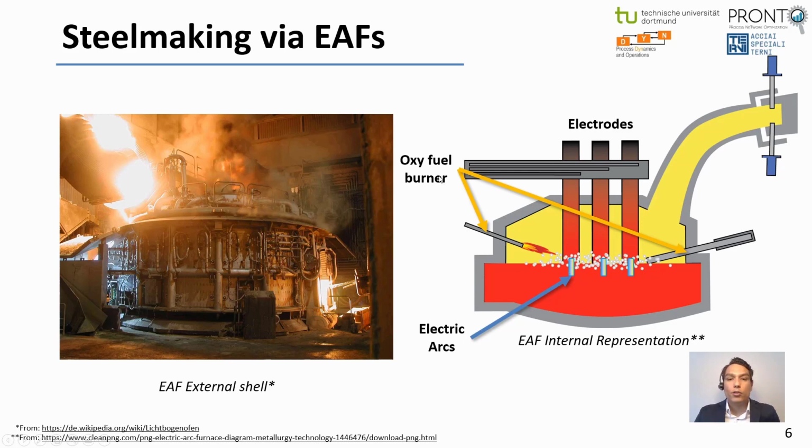We also see the oxy-fuel burners that can be used to introduce methane and oxygen, and they create the oxy-fuel flames at high temperature that aid the melting process, and they at the same time can work as an oxygen lance during the last stages of the process. So you just use the same burners only for injecting oxygen, and this helps to increase the temperature in the liquid bath as well as the refining of the crude metal itself.